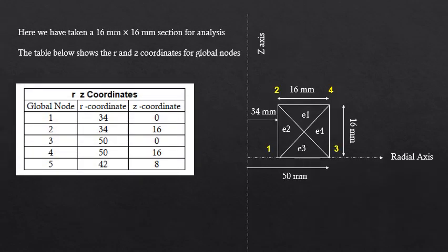The z-dimension of section is taken as 16 mm. Since the boundary conditions and loading does not vary in z direction, the choice of z-dimension is arbitrarily taken here.